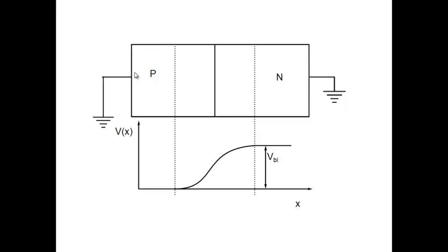This is another picture that we said that inside a PN junction at equilibrium, there is a depletion region here, and inside the PN junction there is electric field and there is a built-in voltage. Built-in voltage exists inside a PN junction. But then, the other misconception that many times students carry is that the cut-in voltage is the built-in voltage.